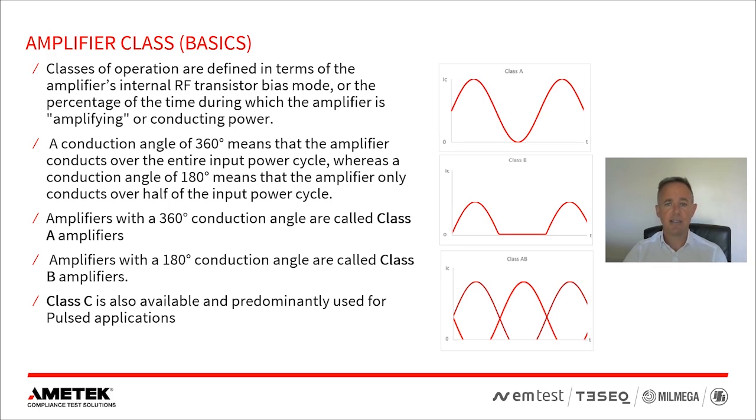At first glance, a Class AB amplifier seems to have several advantages such as lighter weight, increased efficiency and reasonably linear performance. However, they are not suitable for all applications where a really high linearity is required. Plus, they can be more susceptible to high VSWR conditions, which can lead to damage to amplifiers.